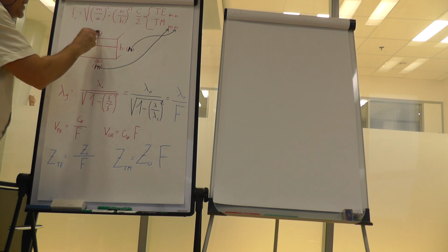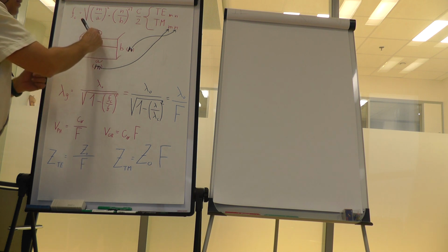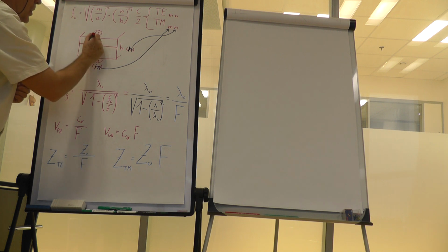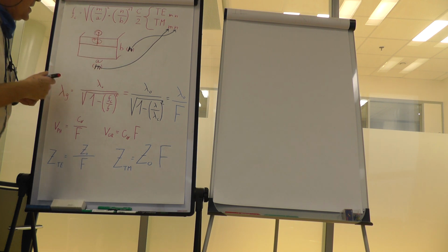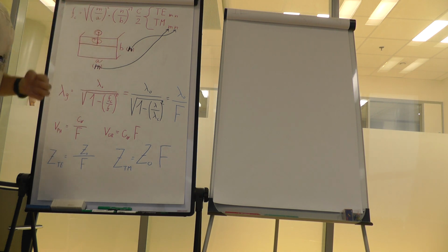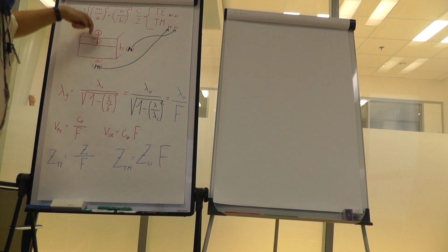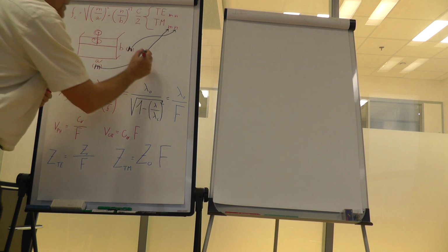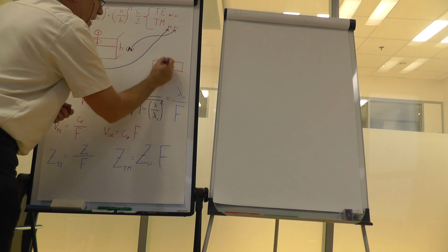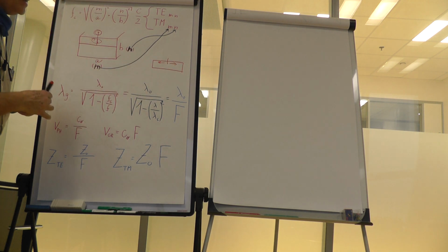So if you connect here some voltage, it will spread some current inside, and the current flowing down would cause the magnetic field over here to be very similar to the field of the dominant mode that propagates. So this would create, in the waveguide, I have here this insert, it would create two waves, one in this and one in the opposite direction.